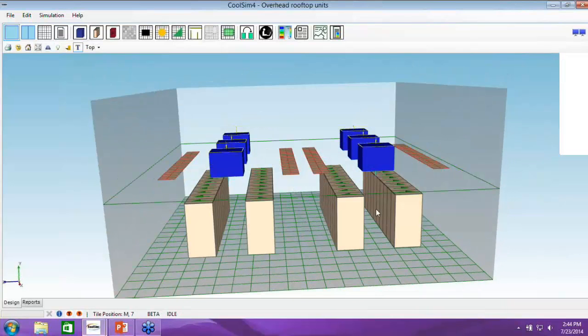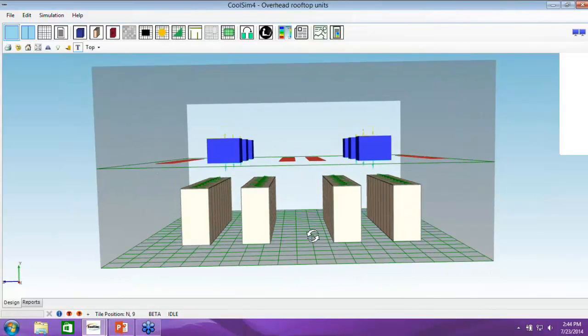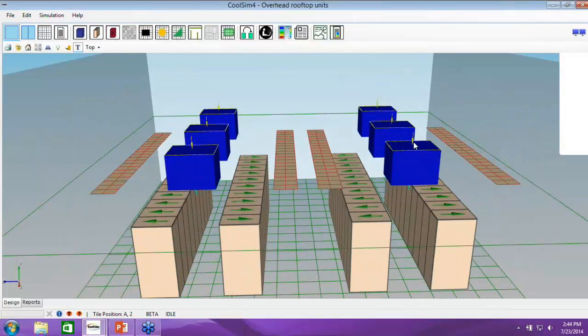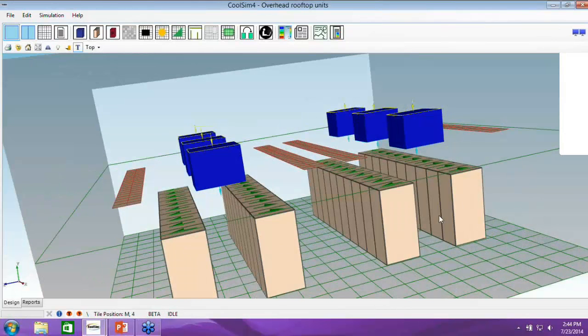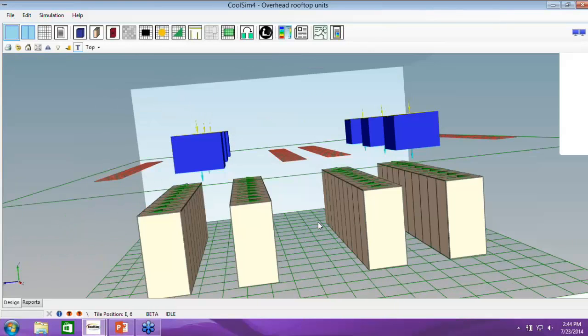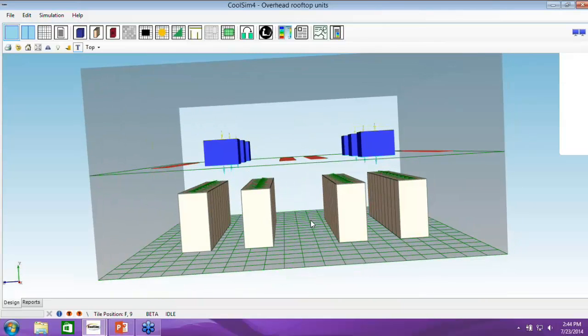And what we have here is a model of what they often call rooftop units. They sit up on top, and they dump air down into, again, sort of a bathtub. It's kind of a bathtub effect, right? You can put end caps on these things, and it would be like a bathtub filling up with cold air. This also could be used to model an air side economizer. So the idea would be the air comes out, goes up through these grills and into the atmosphere. This would be the atmosphere, and from another source you get cold air coming in.